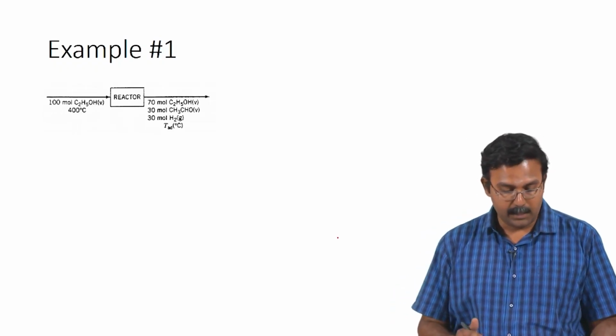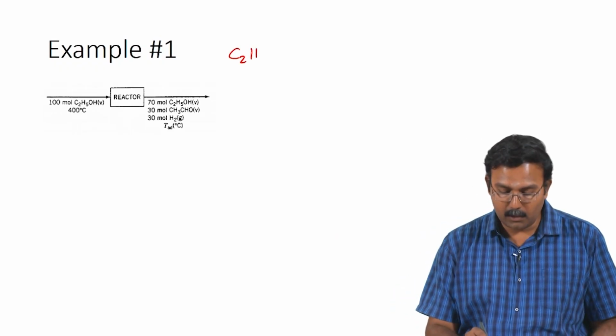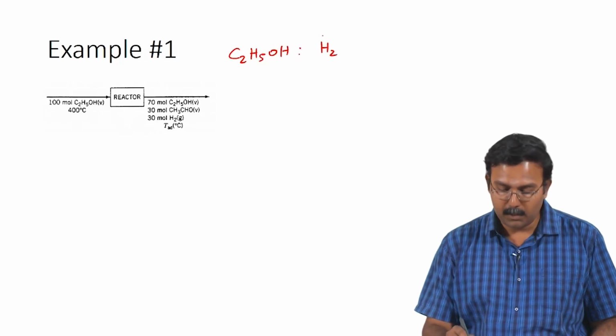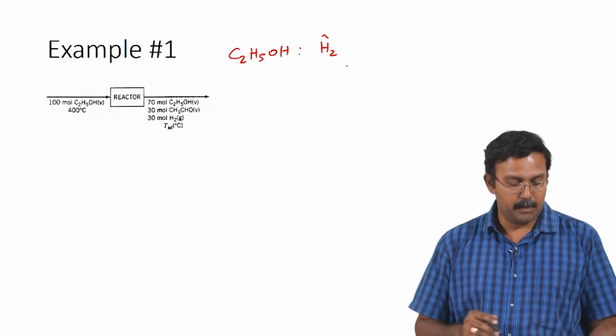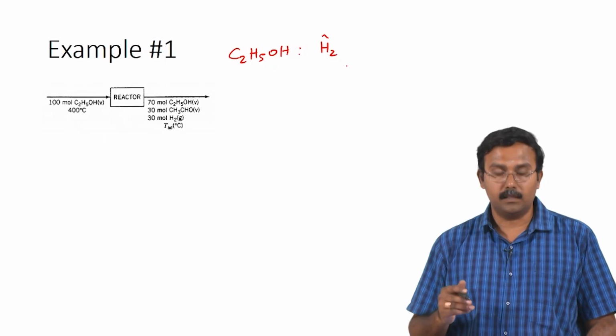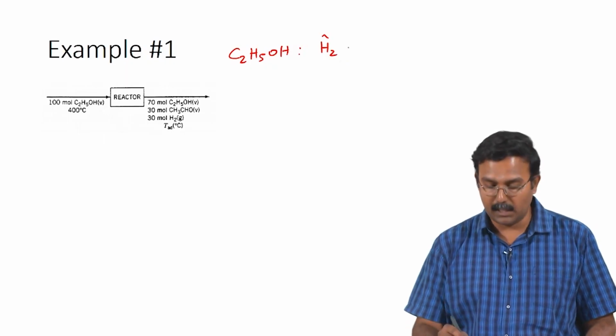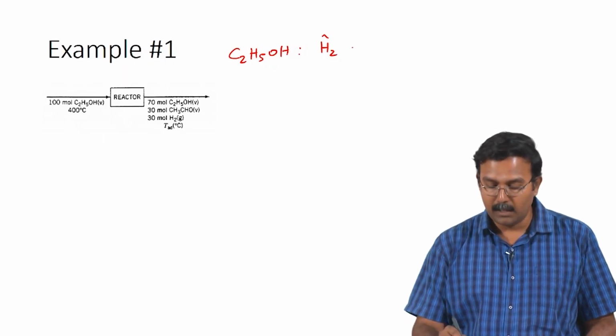So, what we have here, first thing is for ethanol. So, ethanol in the exit stream you have H2 cap. Here the temperature is being increased from 25 degrees Celsius to T degrees Celsius. So, you would have H2 cap equals integral 25 to T Cp dT.